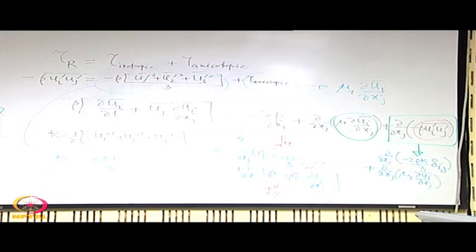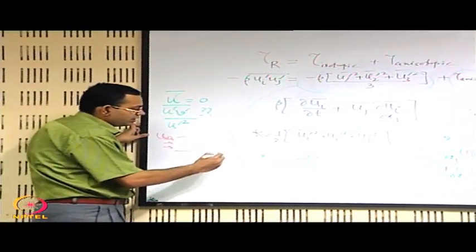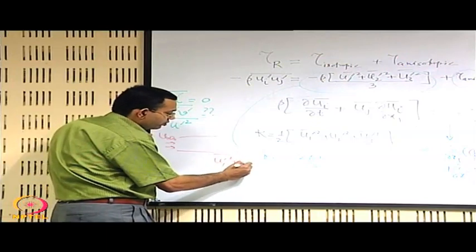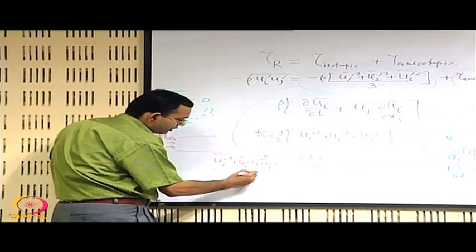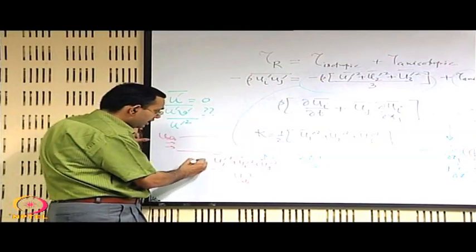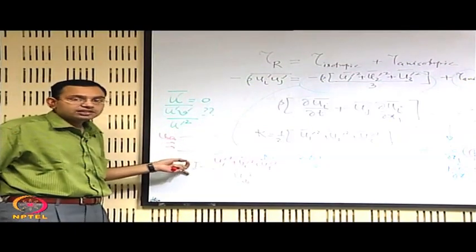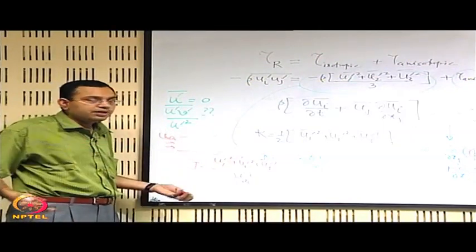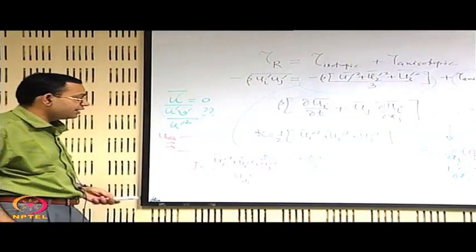So if you have at the inlet of a pipe some flow with a velocity say u infinity, then you may have u1 prime square plus u2 prime square plus u3 prime square divided by u infinity square as a non-dimensional measure of the inlet turbulent kinetic energy, or maybe at anywhere, and this is known as turbulence intensity. And many times it is considered to be a fitting parameter for different mathematical models, maybe 5%, 10%, that is what is commonly taken.